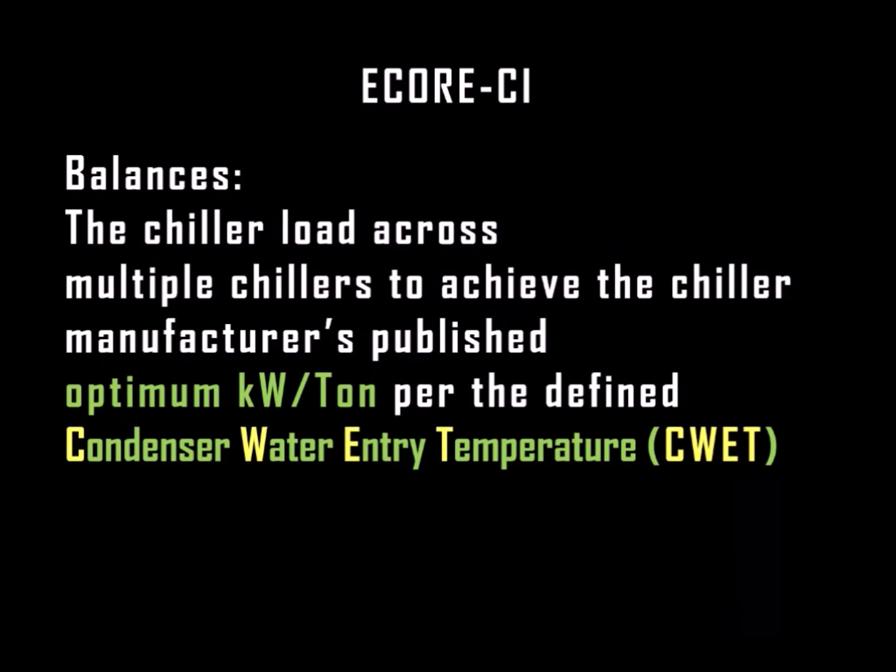ECORE-CI balances the chiller load across multiple chillers to achieve the chiller manufacturer's published optimum kilowatt per ton per the defined condenser water entry temperature.